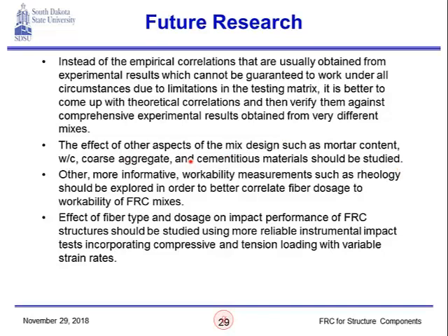further in the future. Other more informative workability measurements such as rheology should be explored in order to better correlate fiber doses to workability. As we know, slump, even though it's a very widely used parameter, and it's very convenient and very easy to perform, especially in the field, that's why it's typically used.